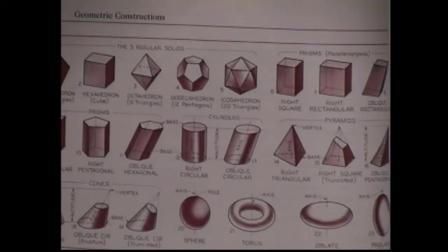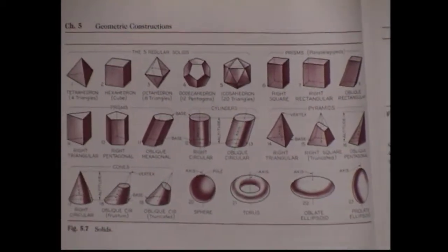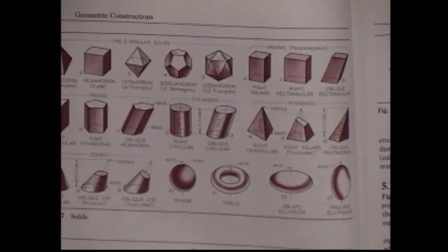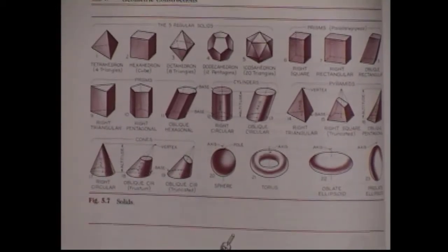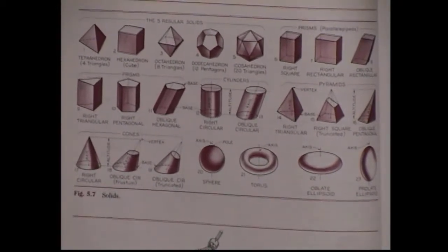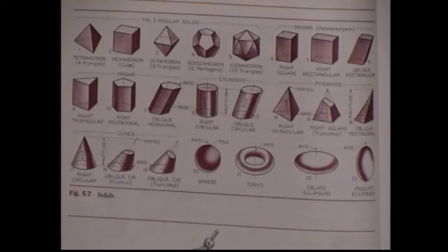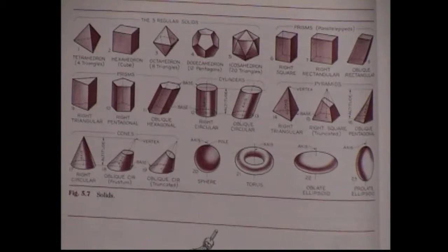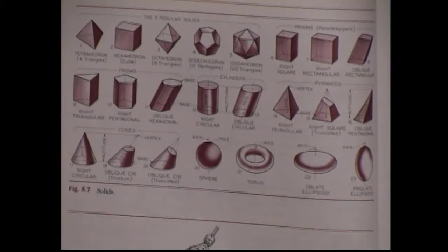And then if we flip over, these are examples of the 3D shapes. When you get into solid modeling, you're actually modeling 3D shapes and just adding them together and subtracting them and intersecting them. There's 3 basic modeling operations: add, subtract, and intersect. So you have to understand, if I put 2 3D models or 3D prisms together, then I'm actually creating a shape.